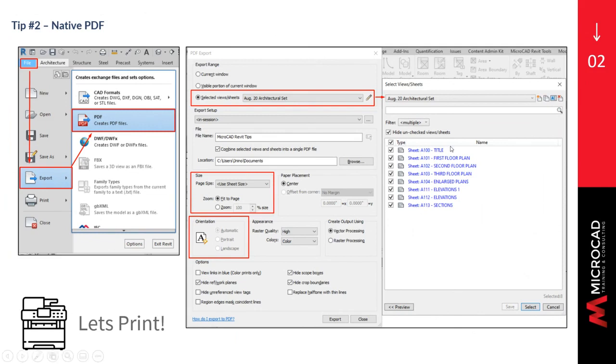You can use this export dialog to offer similar options, such as the ability to export the visible portion of a view, or you can define it from your selected views and sheets. With the PDF naming rules, you may be able to set up all the information that you want for that section of the dialog.